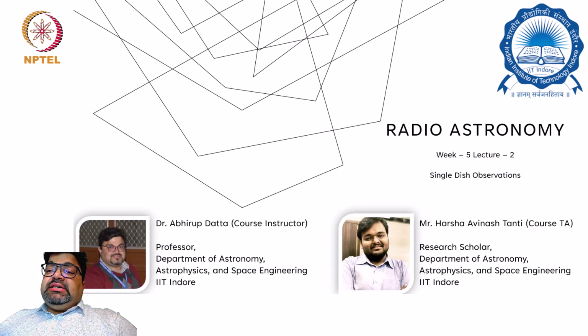In the last lecture, we covered some essentials of radio telescopes, like the reflector antenna design, different types of reflector antenna design, and why a reflector antenna is the most common antenna design chosen for radio telescopes: its larger collecting area produces a sharper beam, with a lesser HPBW or half power beam width, and various others. We also discussed the different reflectors and feed locations: Cassegrain, offset Cassegrain, prime focus, etc.